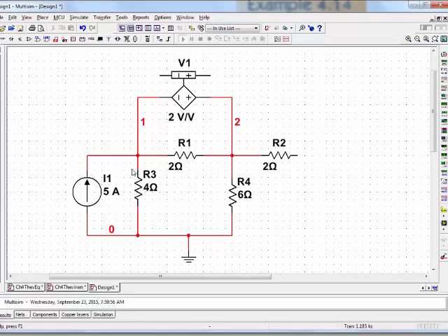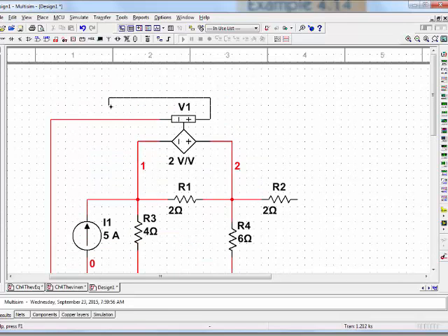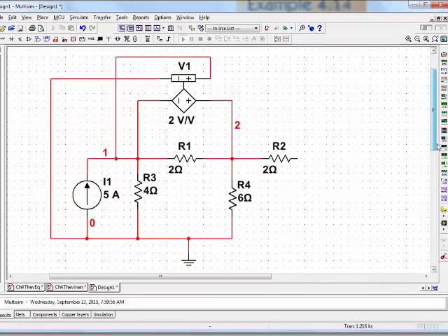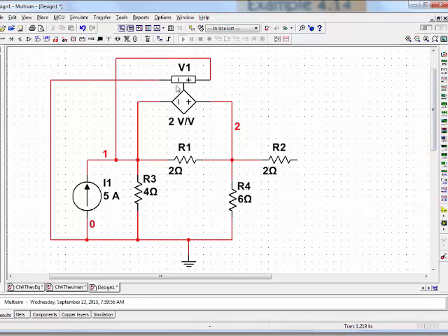I'm dependent on the voltage with this being plus and this being minus that's across R3. So I need to connect this that way because this is its reference point. Actually, to do that, there's the minus side, correct? This is still the minus side. And then the plus side has to be the plus side of R3 here. I don't know what's the prettiest way to connect that. So I think I'll do that. So these nodes are not connected. Now the circuit looks a little bit messy, but understand that this is how I am making this a dependent source.